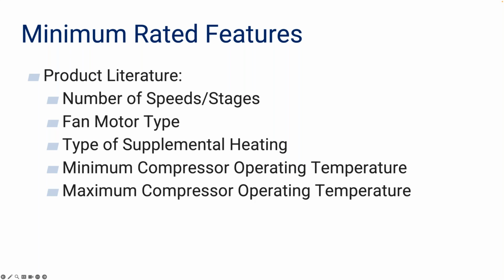And then in some cases, you can actually have these systems without supplemental heating, in which case there's still a requirement that, for at least modeling, you need to have a supplemental heater in case it's needed to meet the load. Because if you're not meeting the load, you're not using energy, and you're basically getting a free credit for not meeting your set points. So the standards require some kind of backup heating.